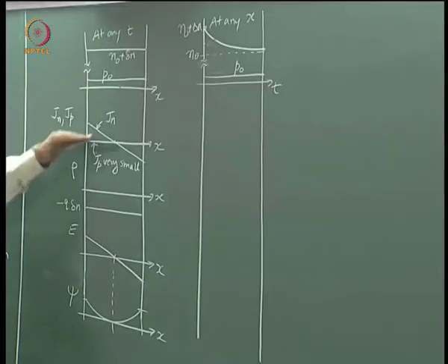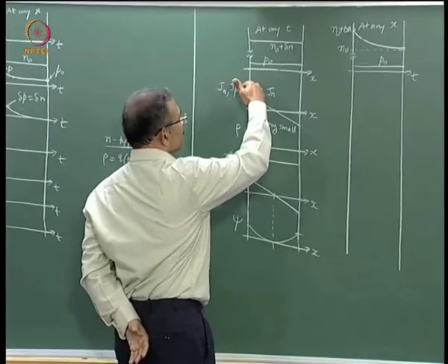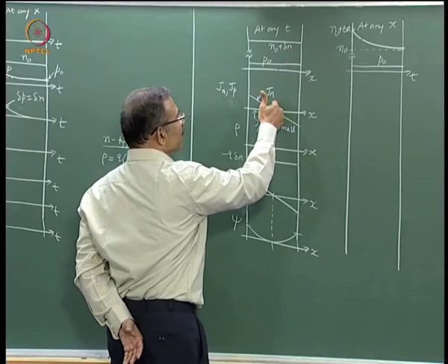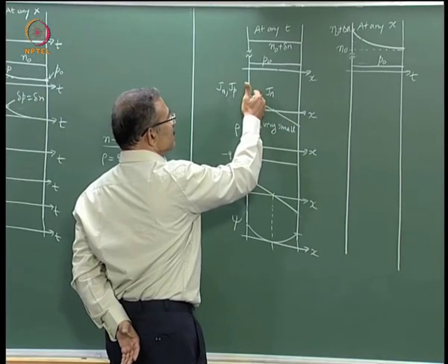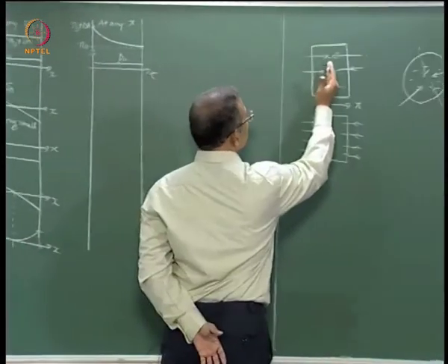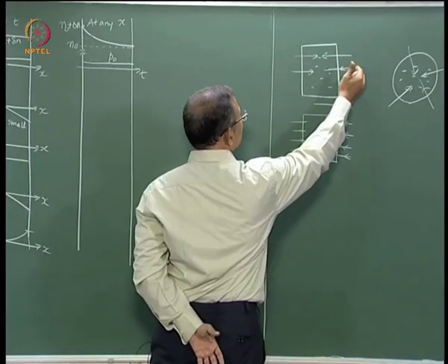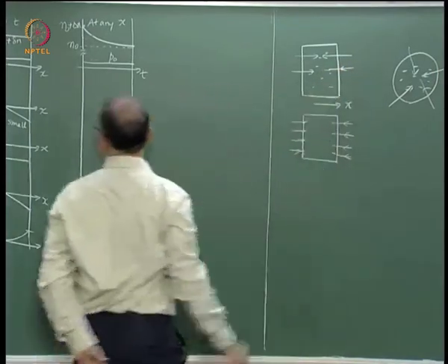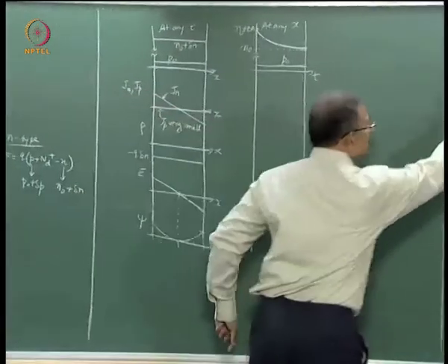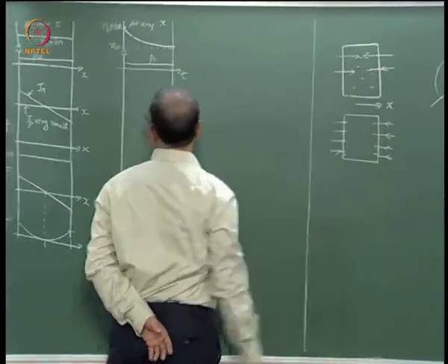So that is your picture for the electron current, hole current, electric field and potential, right? So what is happening is at any t your current is like this, it is 0 at the center, and here it is positive and here it is negative because you see the electrons are moving to the left because of the field, therefore the current is to the right, and here the electrons are moving to the right, therefore the current is to the left. That is what it shows. So at the center you have almost no current, but the current increases as you move away from the center.